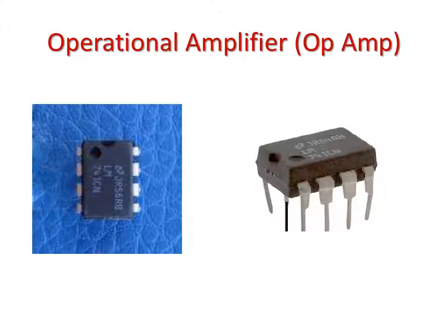Again, we have our operational amp or op amp here, and we've chatted about this a lot in chapter 4. So this is an LM741, which is a standardized op amp. We have a couple others that I recommend. The MCP6004 is another good one that we have a lot of. There's a whole lot of different op amps. When you're selecting an op amp for the job, you've got to make sure that you read the data sheets for that op amp, because the data sheets are going to determine different properties of the op amp that are important.